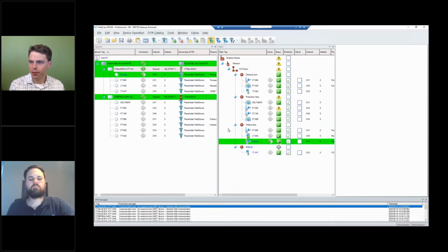And what was the second part of the question? Sorry, do you need a special card to access the HART data from the device? If you have Rockwell, we have a list of supported IOs. The majority of the Rockwell IOs are there. The majority of the Siemens, let's say ET200 IOs, are there. So the HART IO has to support this technology. The FDT DTM must be available, so proprietary solutions do not work. So the card must support it, but for Rockwell, the 7056, the 7094, the 1736, there's a long list, and the majority of the Rockwell IOs are supported by that system, yes.